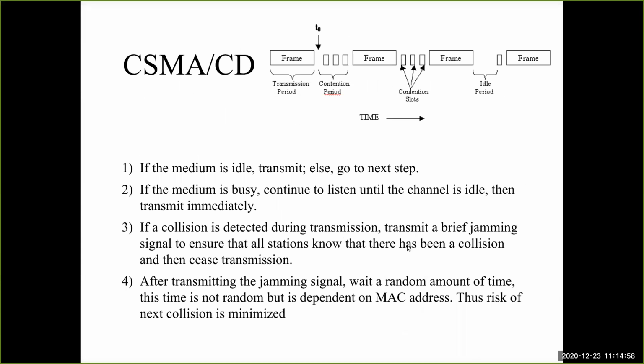So in this case, if a particular node detects the collision, it sends something which is called a jamming signal. The jamming signal is the signal which disturbs everything, like a stream of high and low states on the bus. And in this case, every node is able to hear it, even the node which sent data at the same time and couldn't detect the collision.